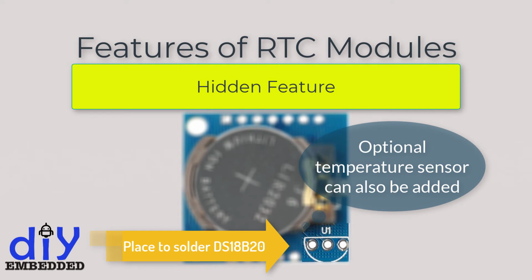Once you install the DS18B20, you will be able to get temperature readings from the DS pin. These readings can further be used to compensate for temperature-based time drift in code. Follow the silk screen to solder the DS18B20. You might also need a 4.7K resistor between VCC and DS.